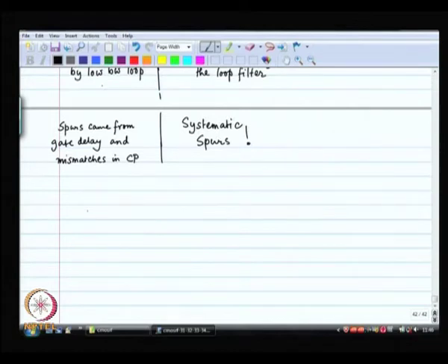Then the integer n case. In the integer n case, the spurs were tiny. I could lower mismatches to 0.1%, I could build faster gates, and so on. I could try to do a lot of things to get rid of the spurs in the integer n case.